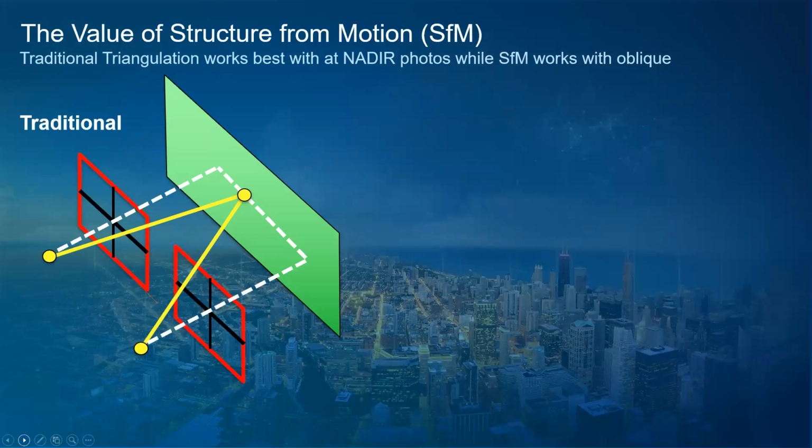Now, Steve Lambert gave a great presentation on our high-end, very rich photogrammetric capabilities. And traditionally, the way that's done is using something called aerotriangulation, where it goes in and it just matches all the images up and produces a mathematical model about those images. Traditional photogrammetry, traditional triangulation, it really likes to have images that are taken as near vertical as possible. In other words, looking straight down.